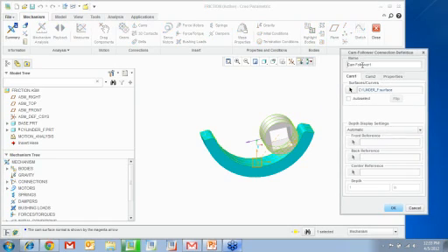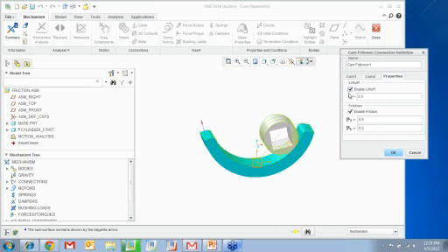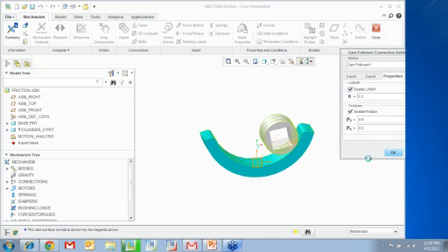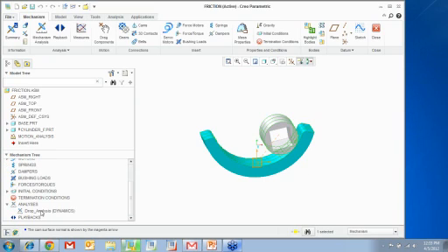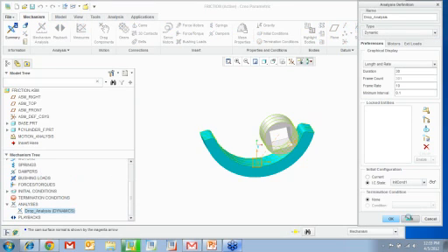You see there's a cylinder surface and then there's the base surface, and here I'm saying enable the lift off, and that is the static friction and kinematic friction values. Now I'm going to run a dynamic analysis and say run, so you can see how it slips, right?